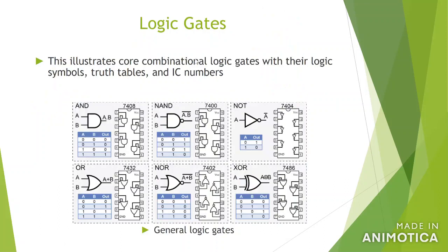So there are all kinds of logic gates. Like I said, we will have an AND gate. 7408 is a package for the AND gate. In this package, you see there are 4 AND gates packed together. These 4 AND gates don't have any relationship to each other. So if in your circuit you only need 1 AND gate, you can choose any one.